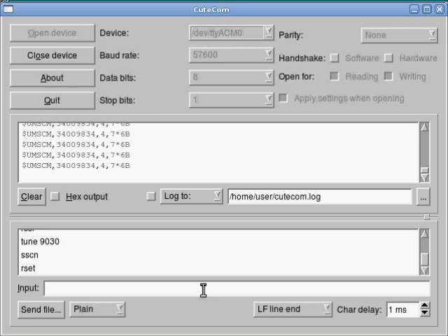It resets the firmware. I can see what version of firmware this is running by using the VRSN command. It spits out a UMVER message, which tells us this is a Grid Insight AMRUSB-1 running version 0.02 of the firmware, and there's a comment here that says this is beta firmware. So three columns: product, version, and comment. This same structure could be applied to other devices and still be compatible.